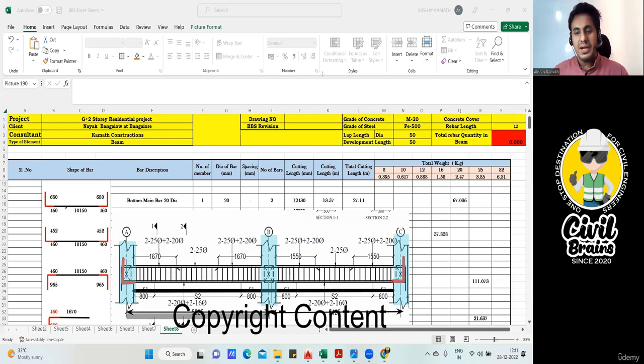But what did I tell you? My concern is from the column inner to column inner. Can you not find this? Very simple. I'll first add this center to this center, and this center to this center. From there, if I remove half face of this column and half face of this column, will I not get the complete length? Obviously, I'm going to get. So I'll do the same thing here.